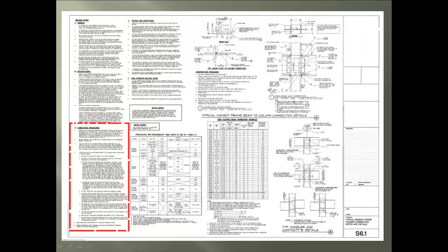Covering items within this sheet specification, here are the minimum requirements for filler metal, the welding procedure specifications, WPS, must be approved by the engineer of record, a pre-construction meeting with the engineer, fabricator, erector, contractor, and inspector shall take place to discuss proper use of WPSs. And here are the requirements for preheat and interpass temperatures. Now we review the fabrication procedures for these special moment frame connections.